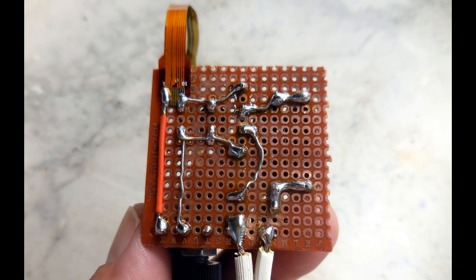All the way to the left, the orange goes between the potentiometer and the cable heading to the LED strip. You can see it says number 1, that's the positive. Off to the right on that ribbon, you can see the 10, and that's where all the neutrals are connected to the output.